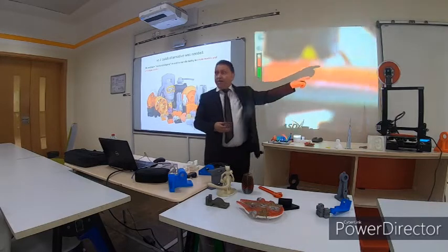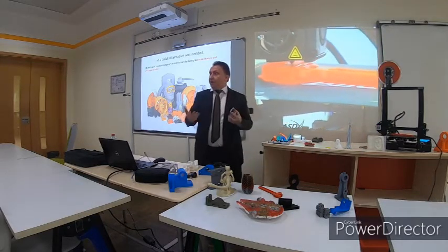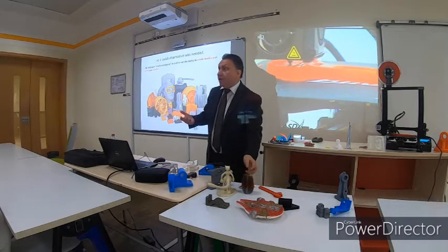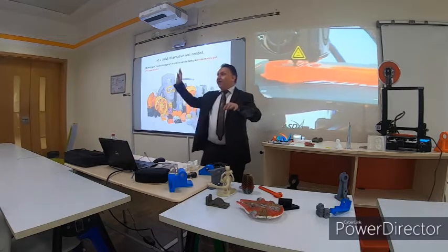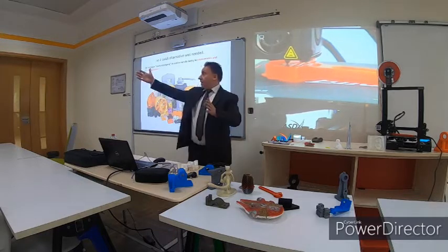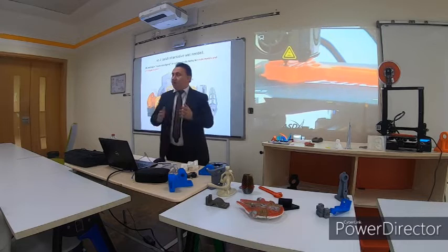You can change the material. Now we are using PLA material. PLA is used for prototypes. It's a little bit fragile. There are some other materials like ABS or polycarbonate, PC. They are used in the industrial brands of 3D printers. There are 3D printers the size of a wardrobe. This is for industry. They use durable materials.